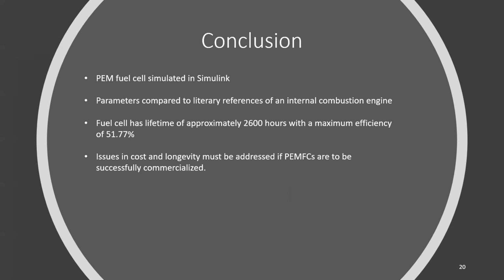So in conclusion, a proton exchange membrane fuel cell was simulated in Simulink, and parameters were compared to literary references of an internal combustion engine. The fuel cell has a lifetime of approximately 2,600 hours with a maximum efficiency of 51.77%. And issues in costs and longevity must be addressed if the PEMFCs are to be successfully commercialized.